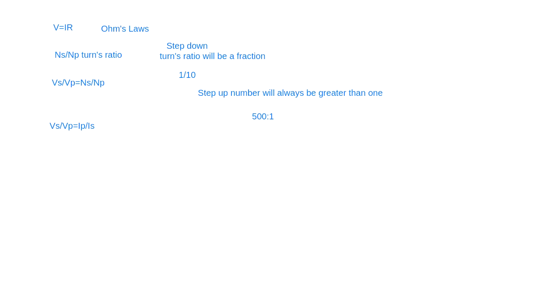So just remember that current is going to be opposite, and then you'll be able to solve the secondary part of that, which will be solving for what your current would be at one part or the other. And usually it's asking what it'll be at the secondary, or it could say this was supplied at secondary, and then you'll have these numbers plugged in and you're solving for primary. It doesn't matter. Just remember that they're inverse of each other. Okay? Is everybody okay with this so far?